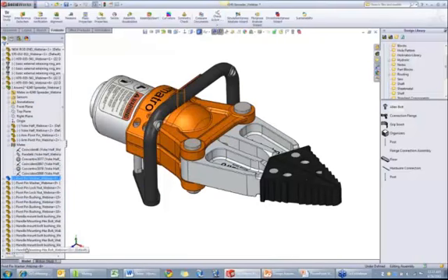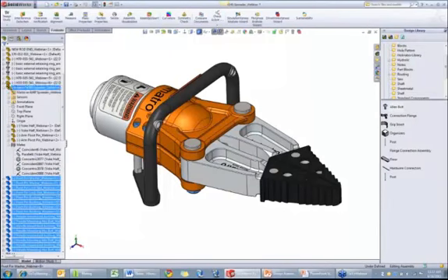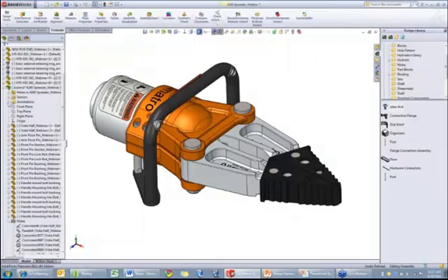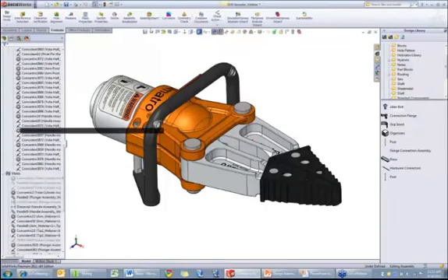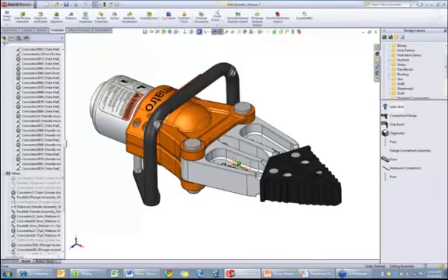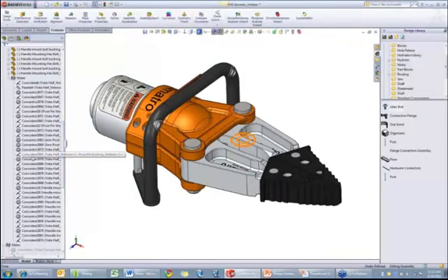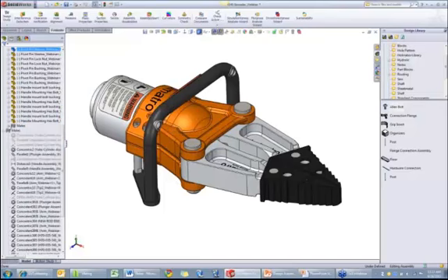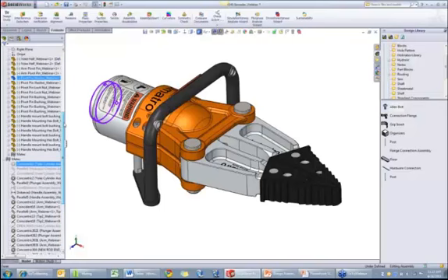I'll grab the rest of these components that make up that sub and move those in. So by doing this, if I go to my assembly expert, I'm down to 39 mates in my main assembly document at the top level. Okay. Now the things you want to watch out for in this case, there are going to be times where you'll have over-defining mates for the location of that subassembly, or if you created an exploded view for your main assembly, you may end up having to delete those steps and redo them.